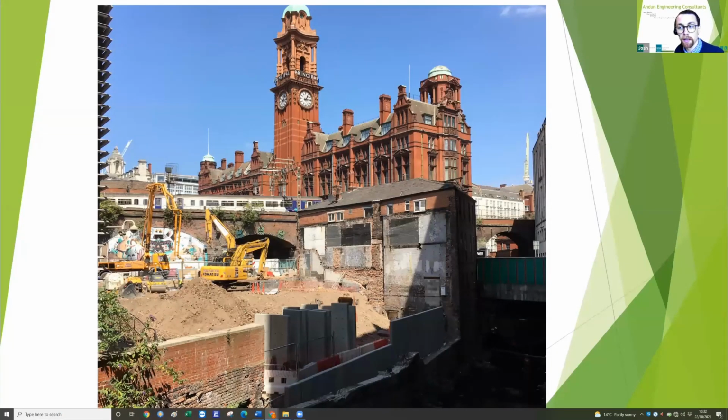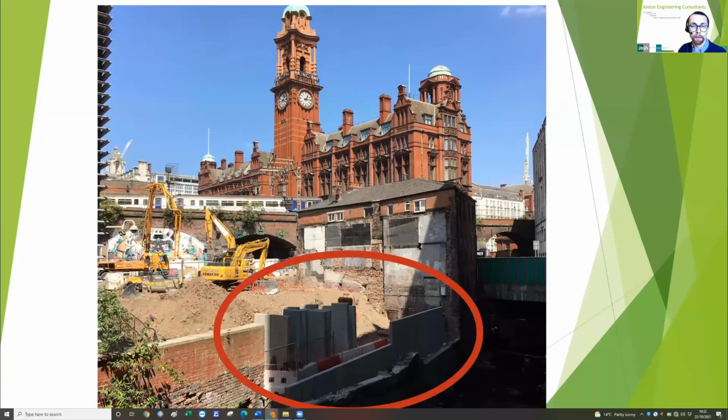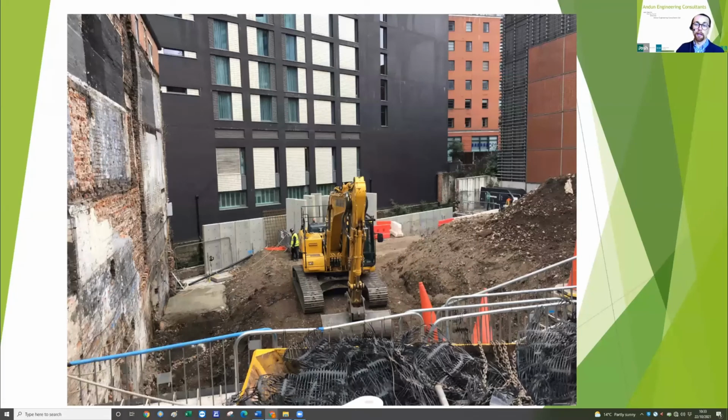The piling works are complete in this photograph, and the reduced level dig can begin. The L walls along the river wall are beginning to be installed, and by having the geogrid steep slope, these L walls along the riverside could start to be constructed way before they finished removing all of the slope works, the high level mat, which links to a combination of different retaining wall solutions to assist the job. Really, it's all working together.